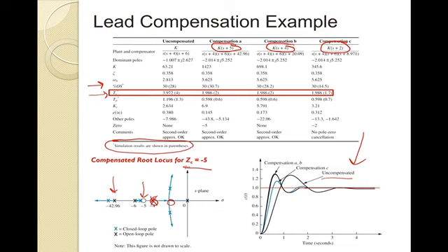This is very important. When we have our three poles, a third order system, and we are making approximations here, notice the following. The percent overshoot in all the cases was 30. That was the desired. But in the parentheses here, these are the simulation results. And so what you'll see for compensator C, here in blue, right there, is that the percent overshoot is about half.